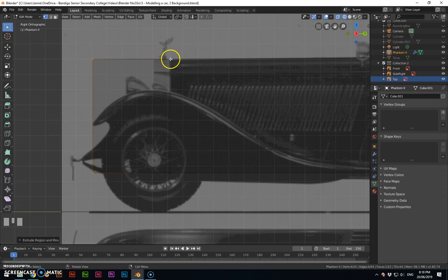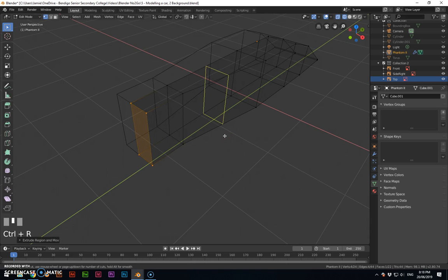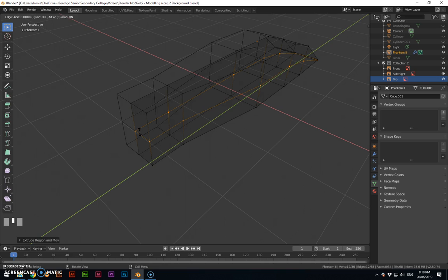This bit though, this bit's going to get interesting because what I really want to do is cut the front off about here and then remove that top chunk. So here's where the next part of the arsenal comes in, is ring cuts. Control R, and if I hover around the shape you can see me adding potential cuts. So that one is probably the one I want, and I can't tell where it goes, so I have to just cancel it and just let it sit there.